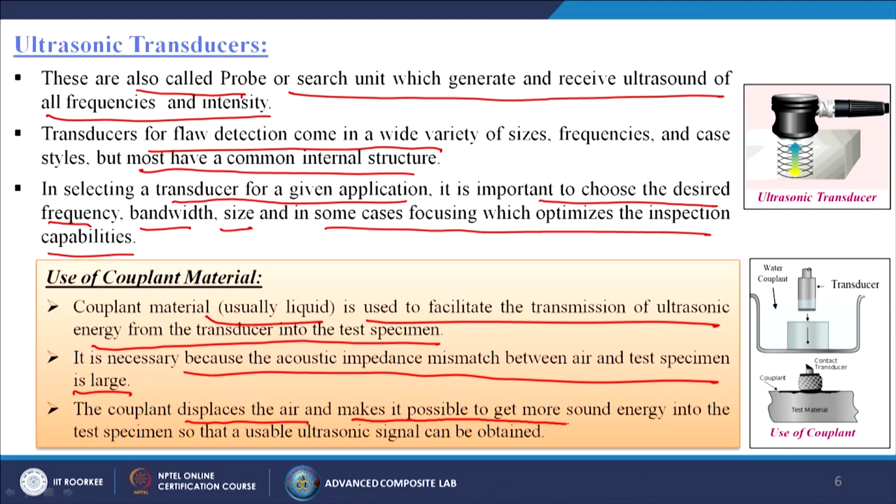So, the couplant displaces the air and makes it possible to get some sound energy into the test specimen, so that a usable ultrasonic signal can be obtained. So now it is clear to us what kind of medium generally we are using.